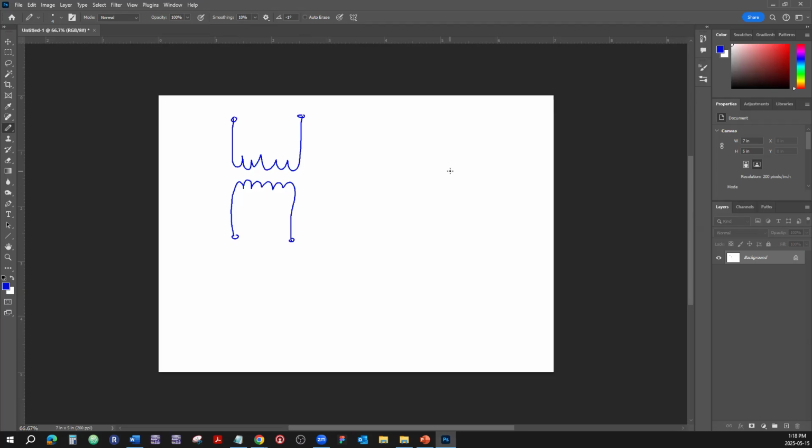Well, by means of induction, because if we have one wire and it's conducting current, it is going to have a magnetic field spinning around it. And if you put another wire beside that in close proximity, so that the magnetic field is going to affect it, it is going to cause a current flow in the other conductor. However, it only works with AC. What does it mean that it works with AC? The magnetic field has to be changing in order for that induction to happen.